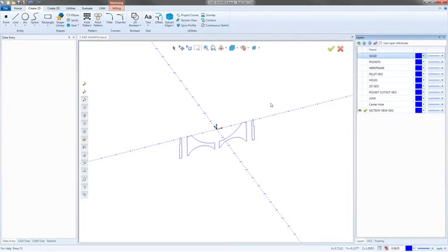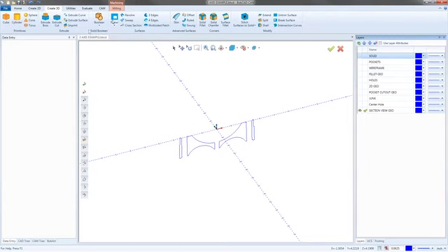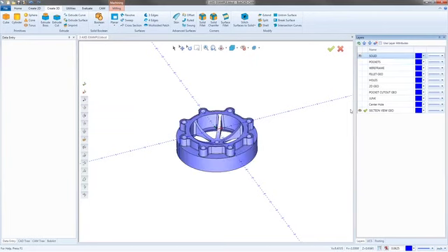The other way to do this, it's a lot more in depth, but you'd have to go into the Create 3D. You'd have to start by making a plane, and whether you use a planar surface or a rectangular plane, you'd have to make a plane that splits that part in half. So I'll just show you real fast. It's way easier. So here it is. I'll make a new, get the check mark up there. Make a new layer real fast.